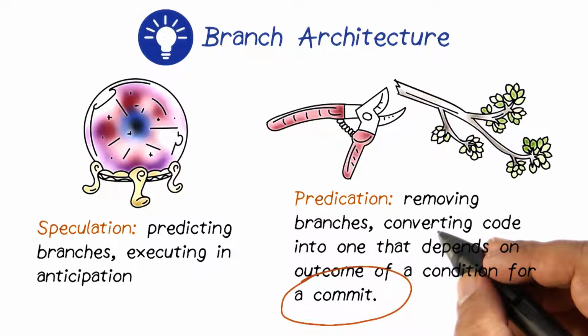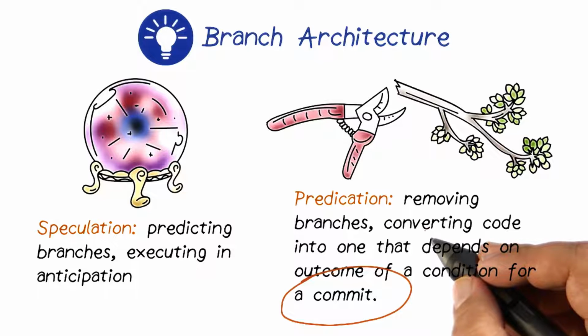For example, if two registers are being added and the result is being stored into a third register, upon the branch outcome being known, we'll go ahead and write the result into the destination register. However, if it is a store instruction, we will, upon knowing the branch outcome, again take the result of the store and go ahead and put it in the memory location.